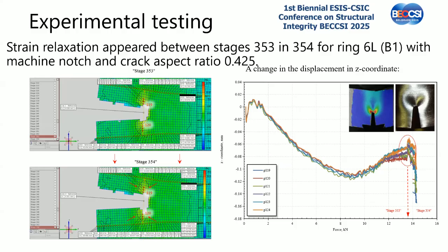Because at the moment when the crack inside the material starts to propagate after the blunting, you have some kind of relaxation that is like a crack closure effect. But actually the crack in the middle starts and makes tunneling, while on the surface you have no crack propagation, but you have relaxation because the material is able to relax to go closer.